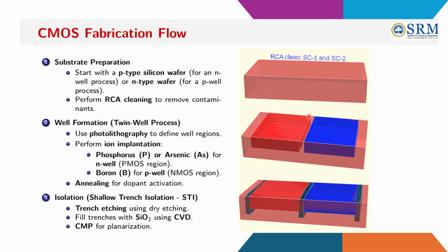The photoresist: we expose it to UV, and depending on where you have kept the mask, the patterns are created on the substrate. So this is the summary of photolithography. I repeat, photolithography needs three things. First, a UV source. Second, a mask. Third, photoresist. And finally, your substrate over which you are going to grow.